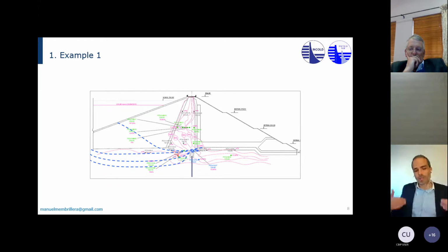With all these emergency works that we've had in the last years, in total from 2008 up to now, 4 emergency works, grouting with cement, but also with resins. So this last time, part of the grouting was done with resins. Every time we've done these emergency works, lots of piezometers have been lost, so new ones have been installed here